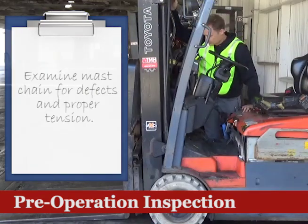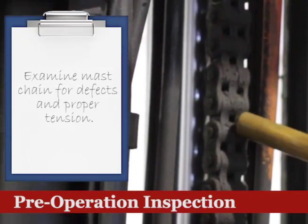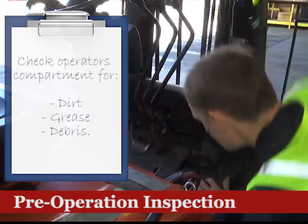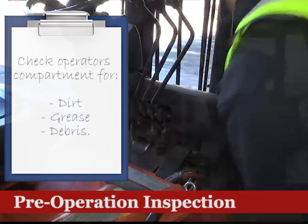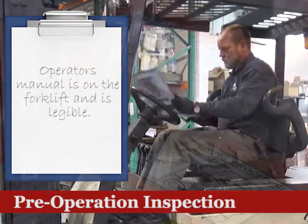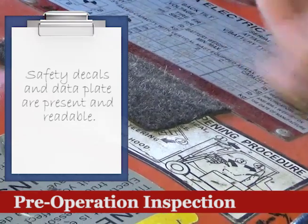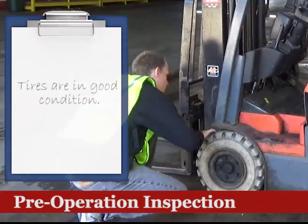Do not place your hands inside the mast. Use a stick or other device to check chain tension. Check the operator's compartment for dirt, grease, and debris. Make sure that the operator's manual is on the truck and it is legible. The safety decals and data plate must be present and readable. Don't forget to kick the tires, and make sure they are in good condition.